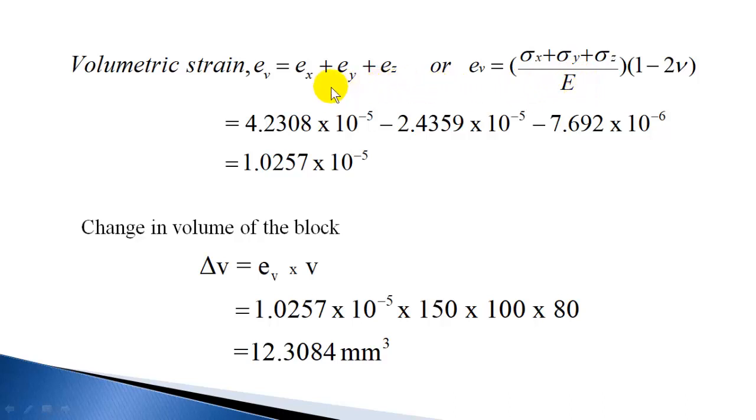You can take it as homework, substitute Ex, Ey, Ez in terms of stresses, Young's modulus and Poisson's ratio. The three expressions derived as a part of generalized Hooke's law, you can substitute and reduce the volumetric strain expression. It is only direct substitution and reducing the terms. If you add, you will get this generalized expression for volumetric strain.